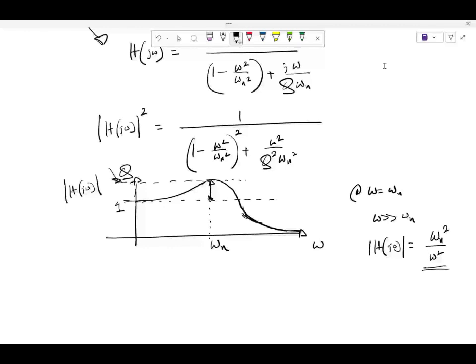Now essentially, the point that we should be mindful of is, just like the time constant doesn't have any meaning unless it's a first order circuit, right? If you have a higher order circuit, the meaning of time constant is not valid. In order to have a time constant, you need to have one capacitor or one inductor, and then the Thevenin equivalent resistance across it, right? So then C times R Thevenin, or L divided by R Thevenin, is essentially the time constant. If you have more than one C and L, the concept of time constant itself